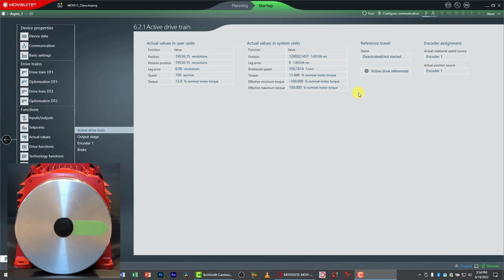All right, next speed. Third speed, works good. Fourth speed, fifth speed, and sixth speed. All right, that works okay. Let's change direction. I'll turn DI01 off and DI02 on. We'll try the same speeds again. Here we go. First speed, second, third, fourth, fifth, and sixth. And everything off.